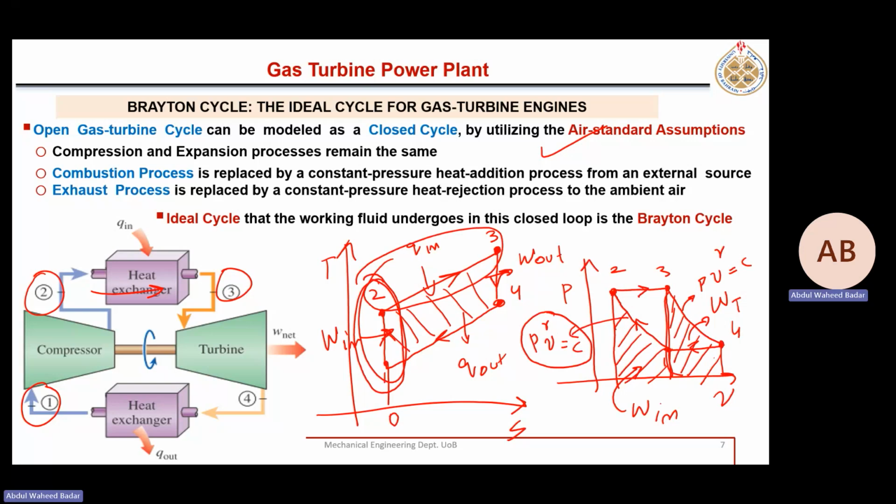Ideal gas, isentropic, constant specific heat, chapter 2 of Thermo 2. The entropy chapter, there we derived these equations. We will be using these equations here in this chapter. P2 over P1 to the power k minus 1 over k. Yeah, it is the same equation.